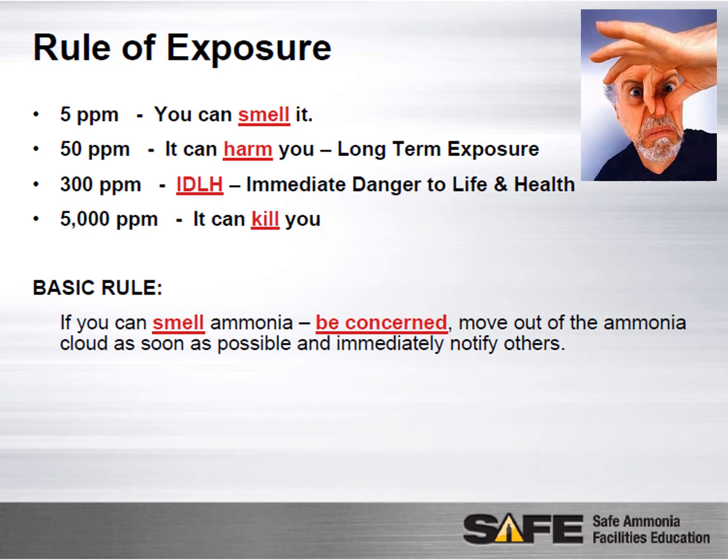At just 5 ppm, so that just means 5 parts per million in the air, you can actually smell ammonia. At 50 parts per million, it can harm you at a long-term exposure rate. That means if you were to work in a 50 ppm environment for 8, 12 hours a day for years, it can cause long-term damage.